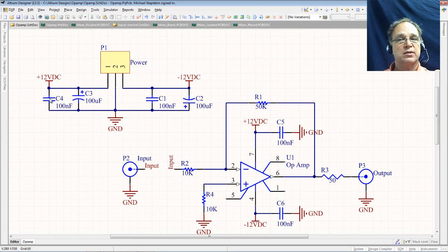But this little capacitor here has a very low ESR. It can dump its current very quickly. It can't hold a lot, but it can dump it quickly. Now this little capacitor might also cost you a nickel in quantity. The problem is these ceramic caps, if I wanted to get 100 microfarads in ceramic, probably cost me $15, maybe $18. They're expensive. Expensive to get very large.